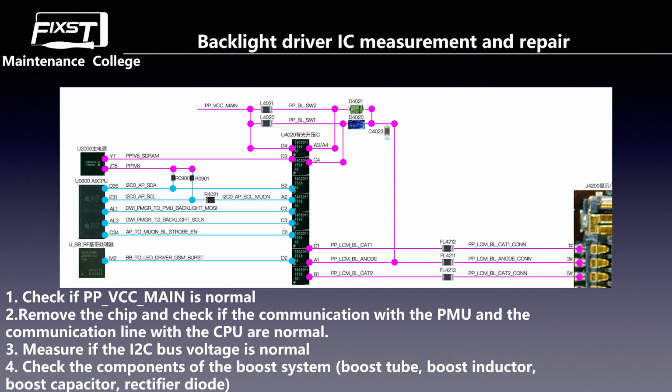And as you can see, C4023 is the boost capacitor. And as we talked about before, here it has two boost systems. One is the SW1, one is the SW2. The SW1 is the boost system for the front flashlight. And the SW2 is for the backlight boost system.